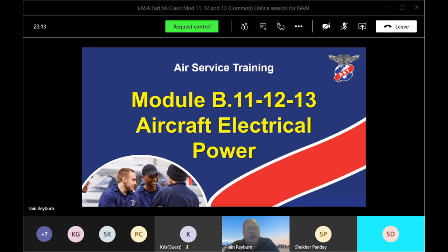Okay, so that's what we're actually going to do in a digital voltage regulator. We're not going to physically change the excitation voltage. What we're going to do now is pulse the excitation field. If the voltage is correct, the time on will equal the time off. If the generator voltage is low, the time on is large, the time off is small. If the output of my generator is high, the time on is small and the time off is large. And that is how we control excitation in a digital solid state voltage regulator.